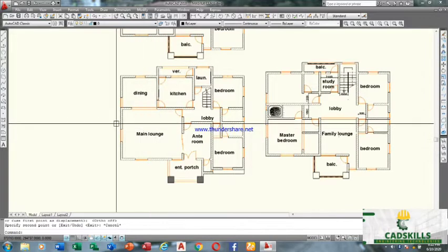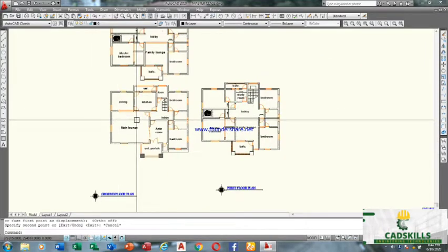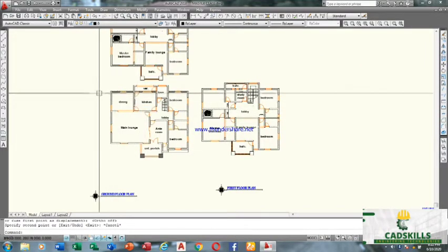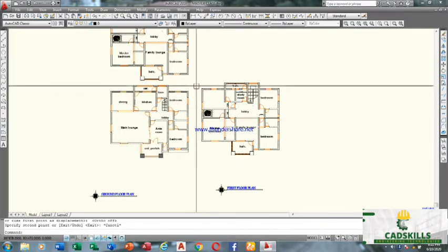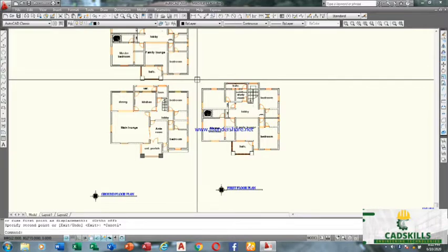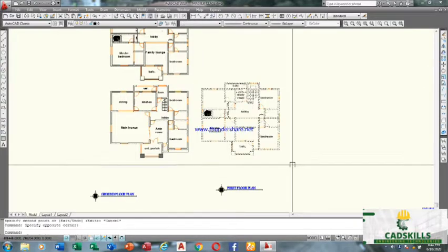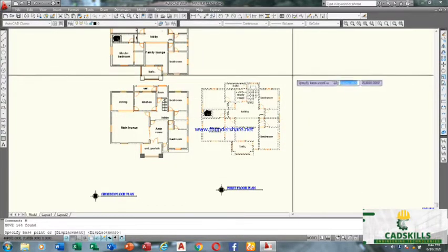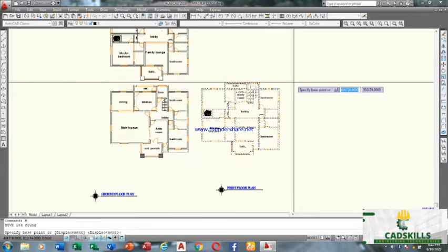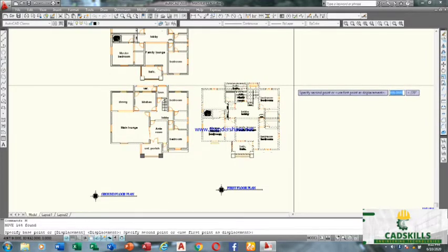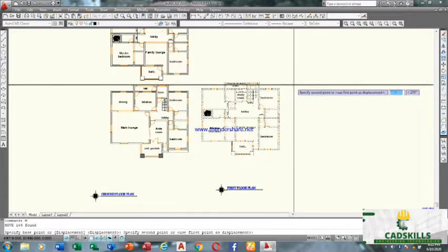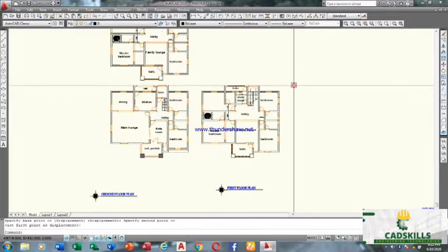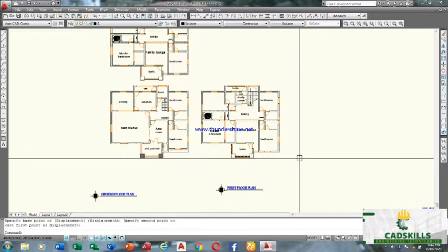Then you now use your cursor and begin to trace. Trace the vertical lines. After tracing the vertical lines, you now trace the horizontal. You can see I have this drawing on the vertical and I have it on the horizontal. That is the upper floor. I paste it according to the alignment so that if there is any projection, I can observe it and take note of it.